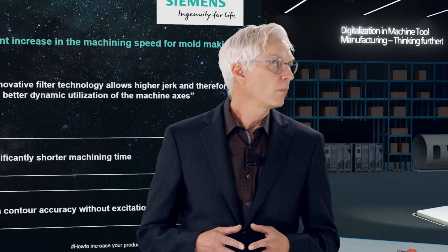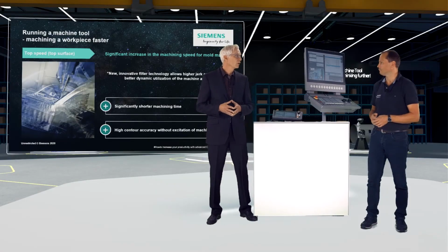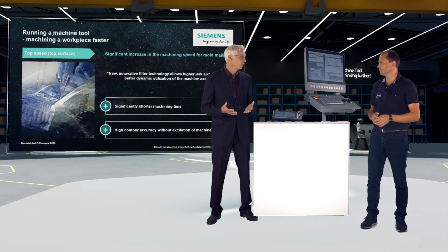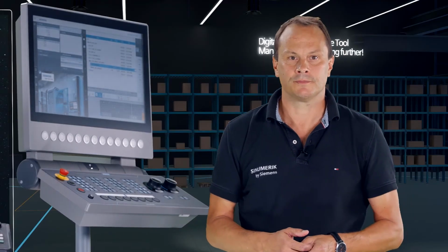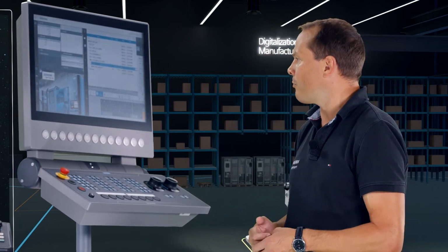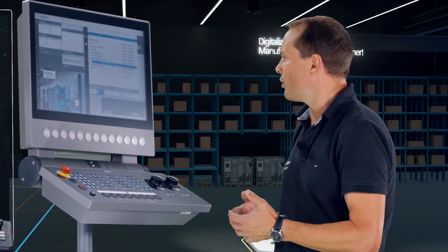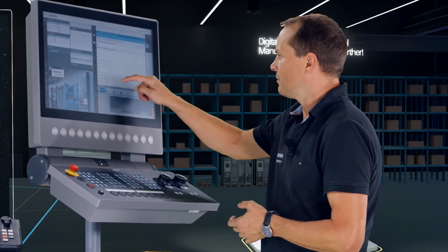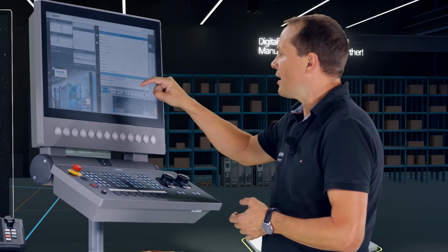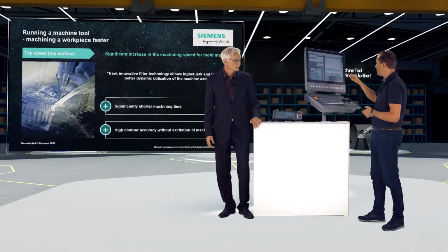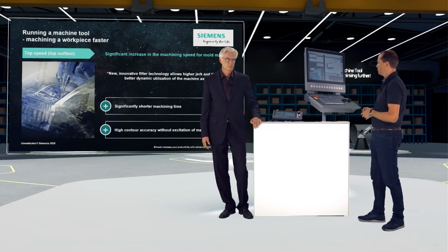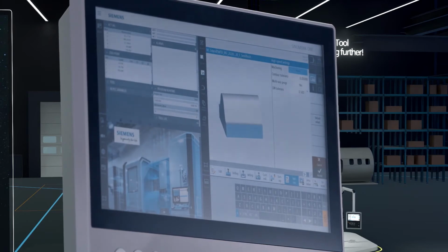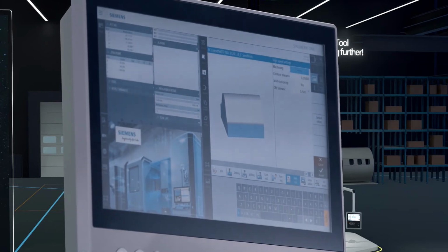Wolfgang, what must a machine operator or a CNC programmer do in order to get the benefits of Top Speed? Sometimes for an operator it's very simple. To show how it works in reality, I just use a mold and die part program and open it. Before cutting, we have to insert, under various high-speed settings, our cycle 832. This is our cycle to transport all necessary functions to get the functions Top Surface and Top Speed.